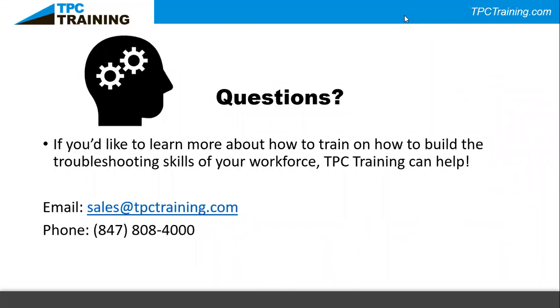The next question might be, okay, what type of gloves do I need to wear? It has to match the voltage rating. Usually class 0 gloves are standard for anything at the 480 volt level, which has the red label on those gloves, class 0 rated for 1,000 volts of usage. But it really depends on the application. So just be careful of that.